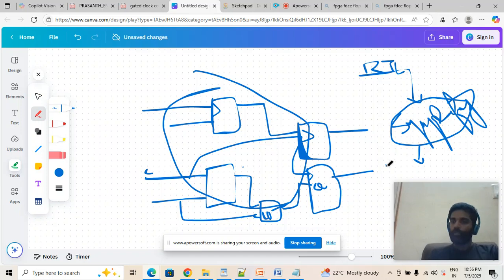So with this netlist, you can go to some backend tool. Now you can go to Vivado, and Vivado will take it. It will be a technology specific netlist file, because when you do synthesis, you have to specify which device you want to implement at the end. So you will go for this Xilinx FPGA, and you will have to mention the FPGA family. So the netlist will come in the form of a technology dependent netlist, for whichever FPGA device you want to go for. Once you get the netlist file in EDN or EDIF format, you can go to the Vivado backend tool implementation.